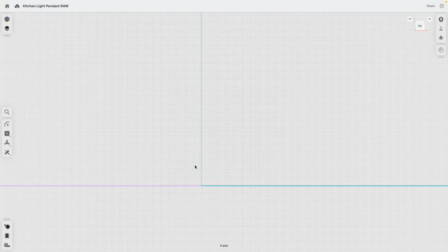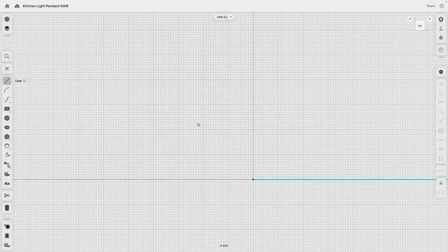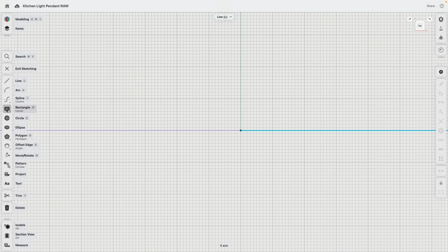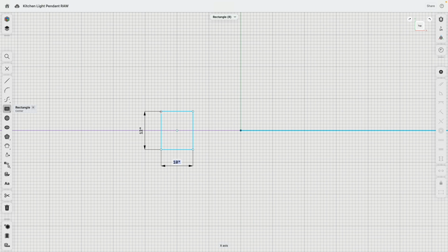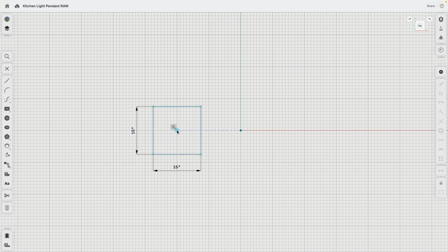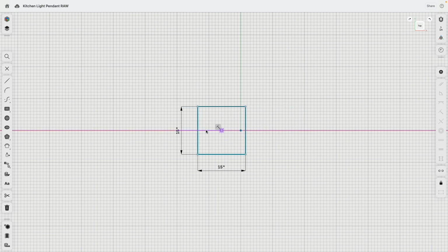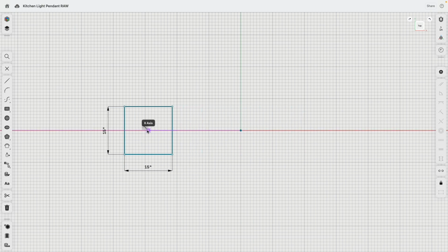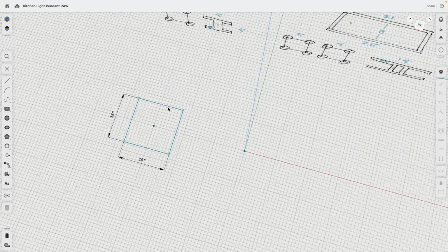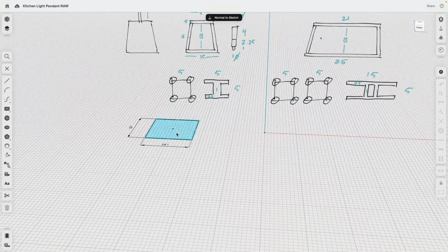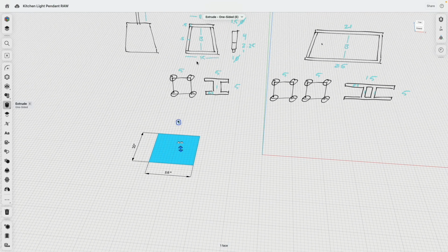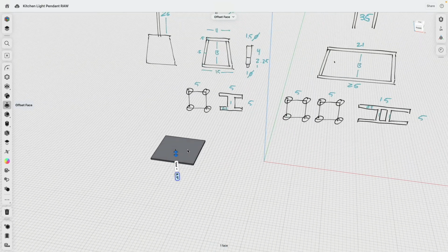So we can go to top view, then go to sketch, zoom in a little bit, rectangle center on any of these grids. Let's say this one, I create now a sketch 15 by 15 and escape. This is coincident on the x-axis. I simply position this here on a nice grid and then click lock. Very good.